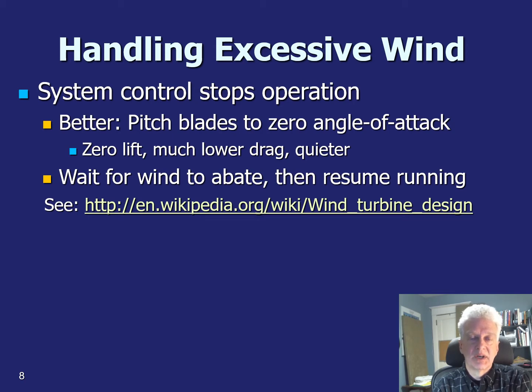Then again, the design is to have the sensors watch for, say, a 10-minute average to go below a designed cut-back-in speed. And when the wind gets back there, then the controls would change the pitch back to the direction where they have lift and they begin rotating again.